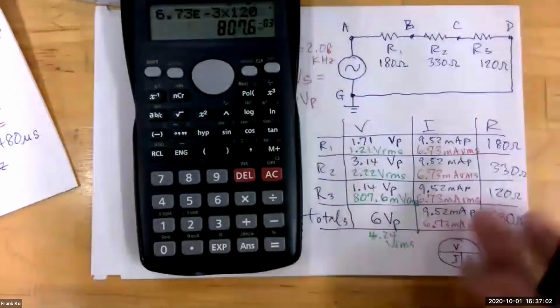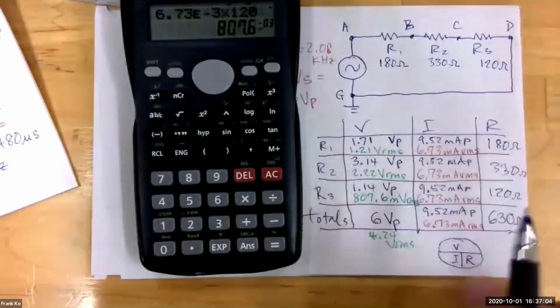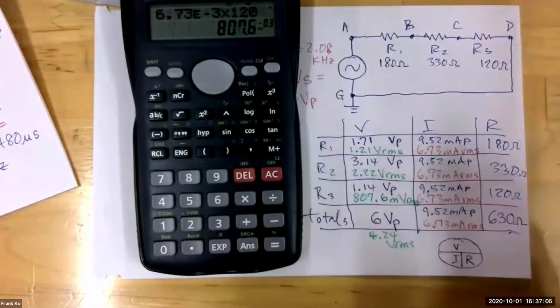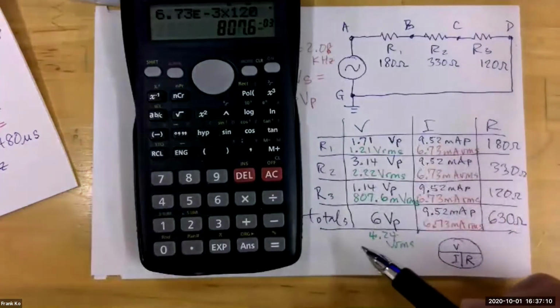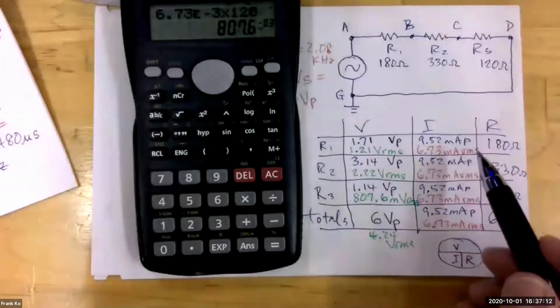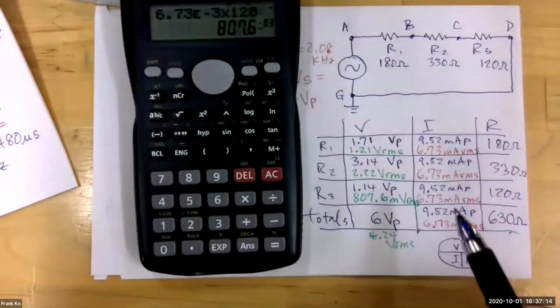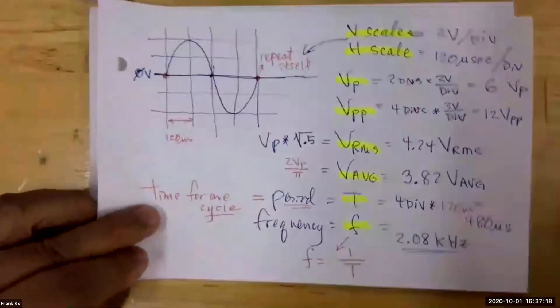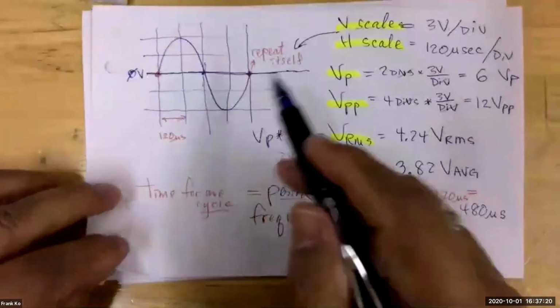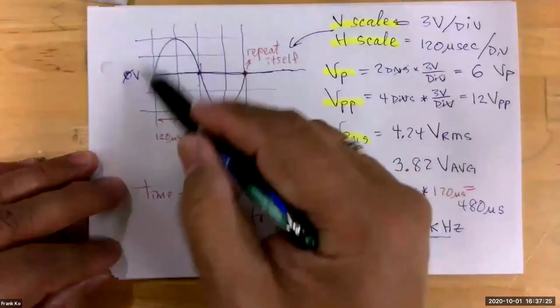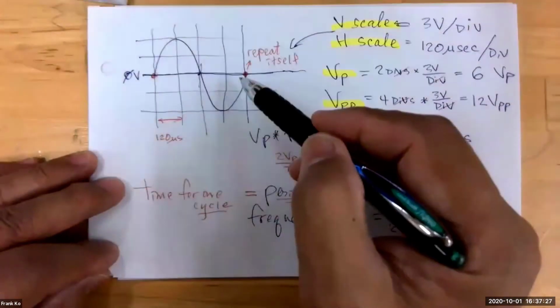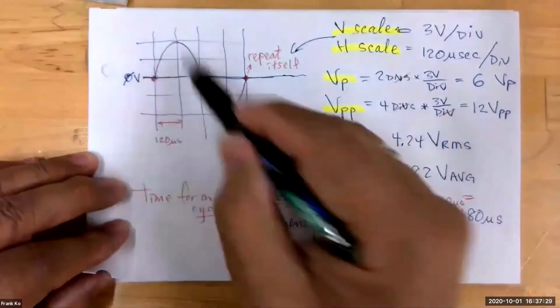The reason we want this table filled with both versions is because the oscope is going to show us the peak values, whereas our digital multimeters will show us the RMS values. Keep in mind, the oscope is designed to show you waveforms, whereas your multimeter cannot do this.